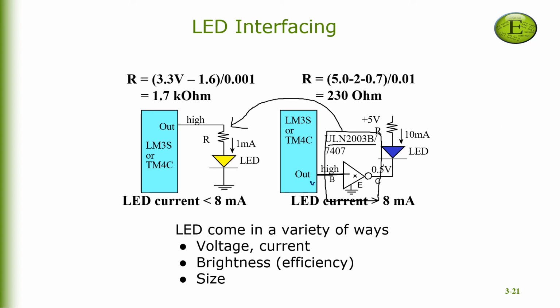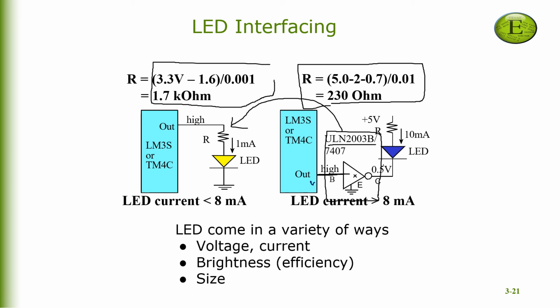And accordingly, you have to calculate the values of resistances. A lot of the time, this step is ignored, resulting in the malfunctioning of the microcontroller. So choose your resistance very carefully, and for that you need to understand the current requirement of the microcontroller, and also the IC that is connected between the microcontroller and the LED.